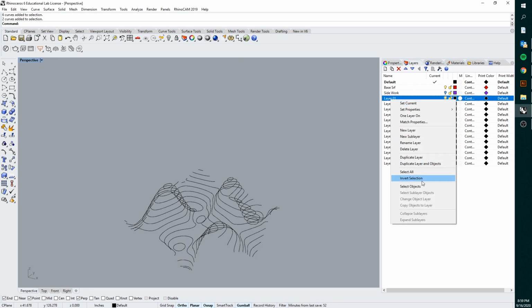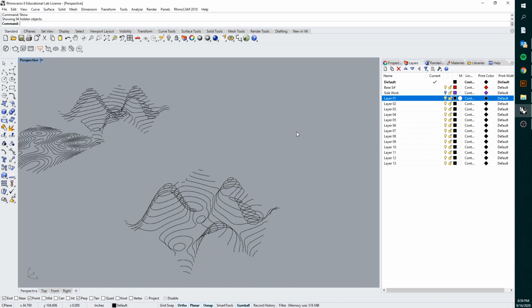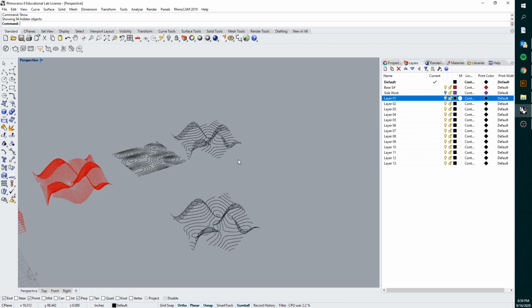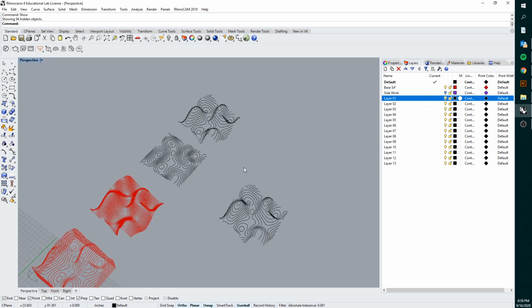And then just the objects on this layer, and move that down. So now if we go ahead and do show, we'll see that this model actually matches this model totally. So that's how you would basically take your two-dimensional drawing and make it back into the three-dimensional drawing.